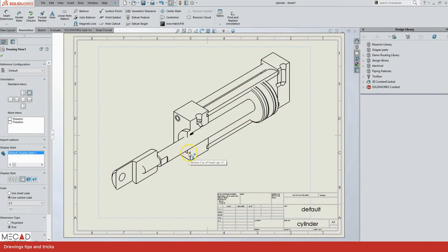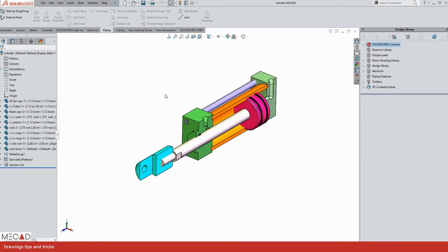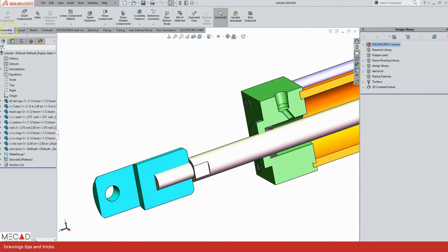We've had support calls from people in the past where we have strange graphics anomalies like this, and users think that there's problems with the drivers or problem with SOLIDWORKS, but actually it turns out to be something quite interesting. If you notice strange lines that disappear, 99% of the time the culprit is caused by interference in the model. So what we're going to do is run a quick interference detection on these two components, and you will actually see that they're interfering with each other.